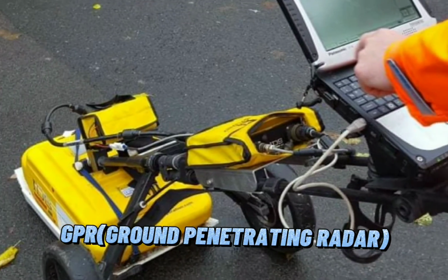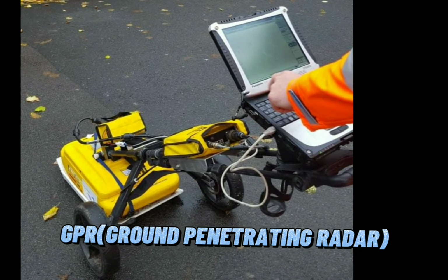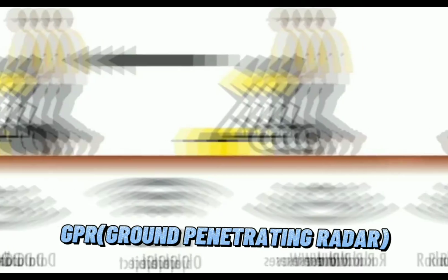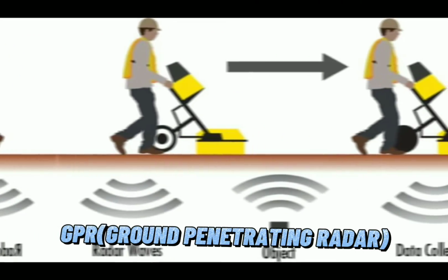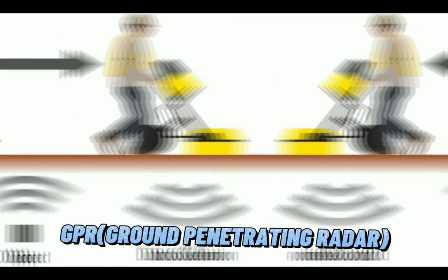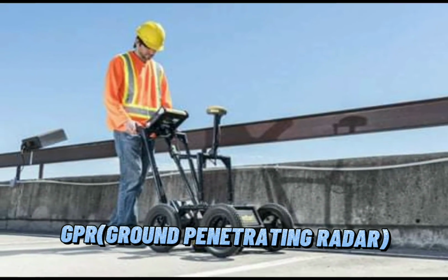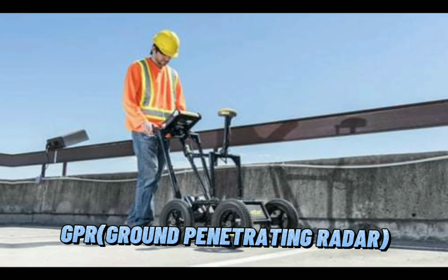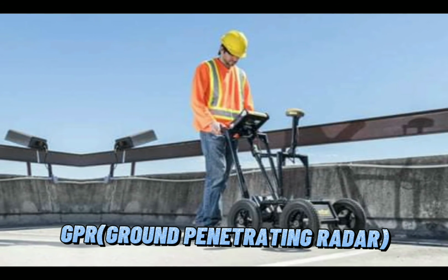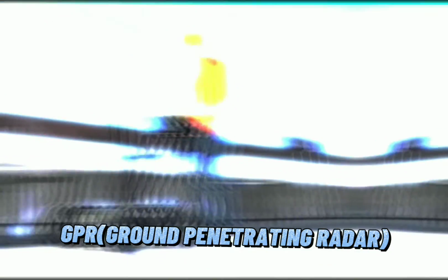Ground penetrating radar, or GPR, method. This non-destructive test uses electromagnetic radiation to image the subsurface of the concrete and detect changes such as delamination, voids, and cracks. Advantages: provides reliable and objective quantitative data regarding the health of the concrete structure early on, rather than subjective observation taken during a visual inspection, for example. Disadvantages: requires high energy consumption and an expert to interpret the data.